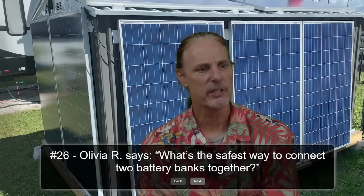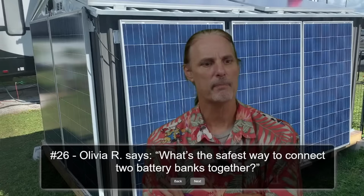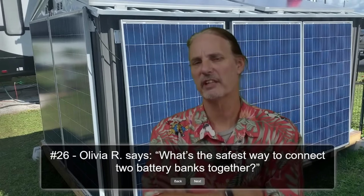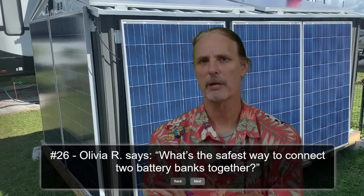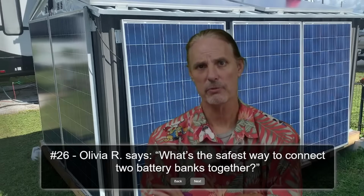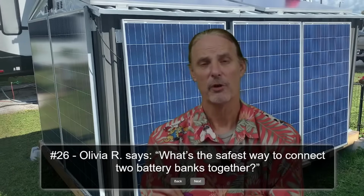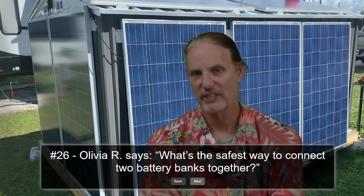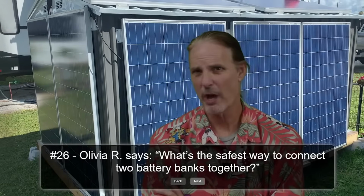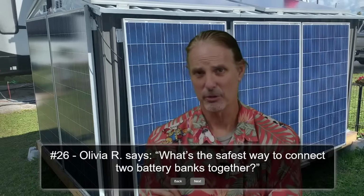All right, so Olivia R says, what is the safest way to connect two battery banks together? We've really gone over this question, but because it's specifically asked, I'll go over it one more time: bring them to the same voltage. If you're not familiar with a meter, or with measuring the voltage of the batteries, the safest way is to fully charge them all. They'll all be at the safe capacity at that point, and then you can turn them all on at the same time. Don't do this while there's a large load. Allow it to be fairly idle at the time that you do it.